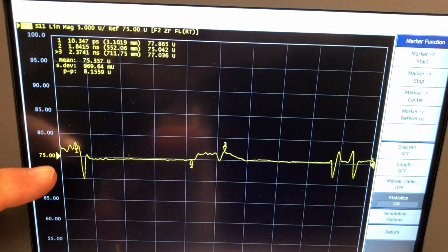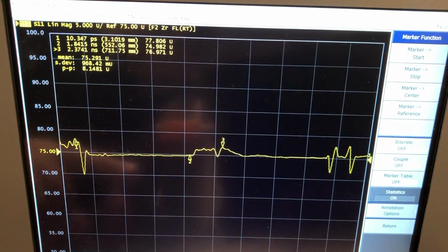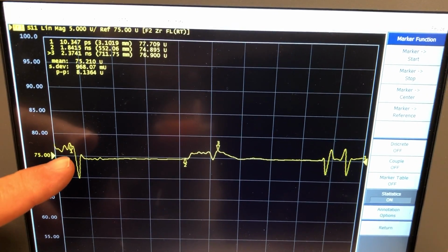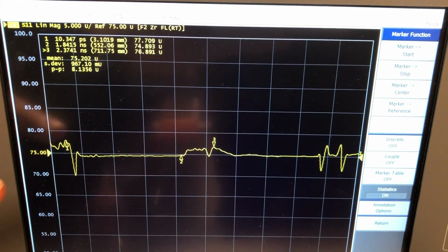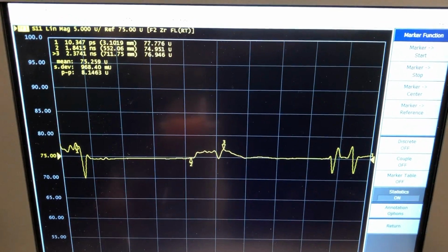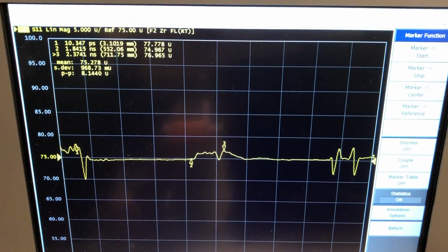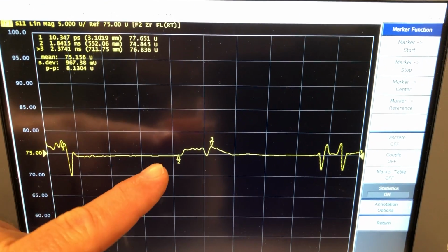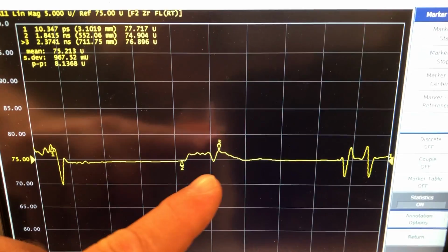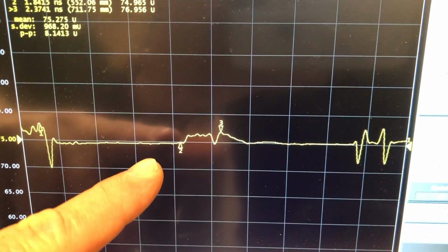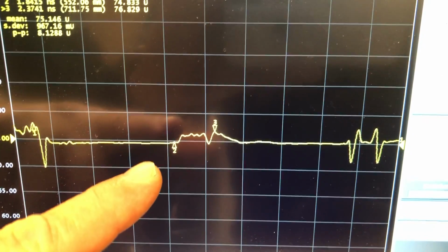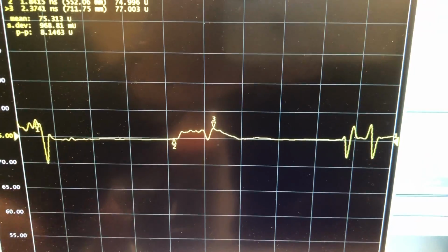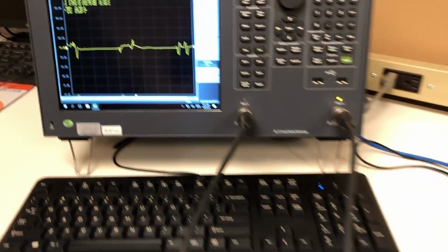What's important here is that this little dip here is actually the HDBNC connector, and that's pretty typical of what we've seen. The deviation is within the tolerance of the CXP-12 spec. But very important is right here in this section is the rotary coupling. So Ray can show you the rotary coupling.